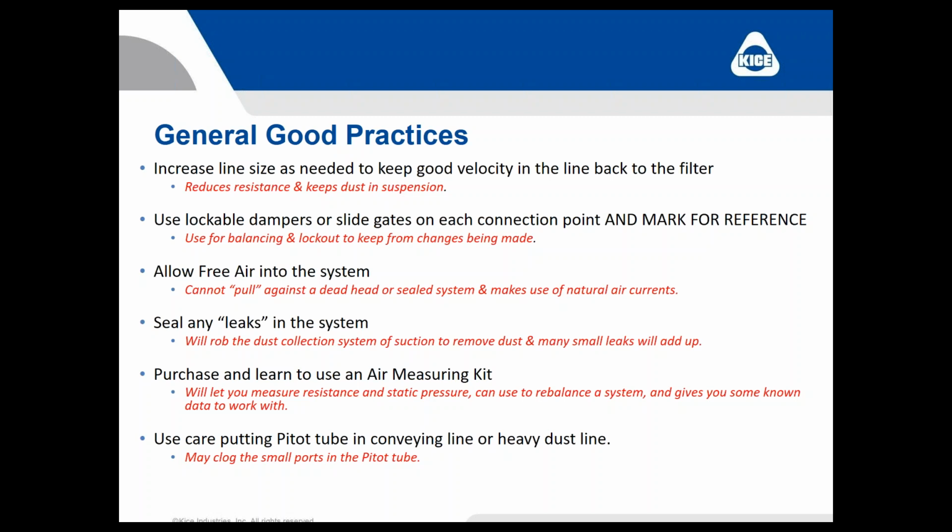Purchase and learn to use an air measuring kit. Obviously, Kice has one. I'm sure there are lots of folks who probably do. You learn to use it, learn to measure with it, and it can give you some good data. And use care when putting your pitot tube into the conveying line. Those small ports can plug. Now, we provide a little clean out tube with it that can clean out some of those tubes, but if you put it in a flour conveying line, chances are you're going to pack enough flour in there, it's not going to come out.